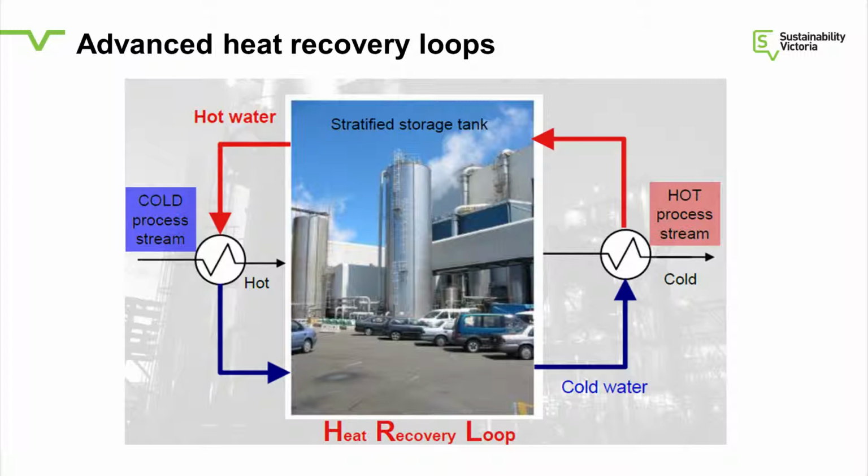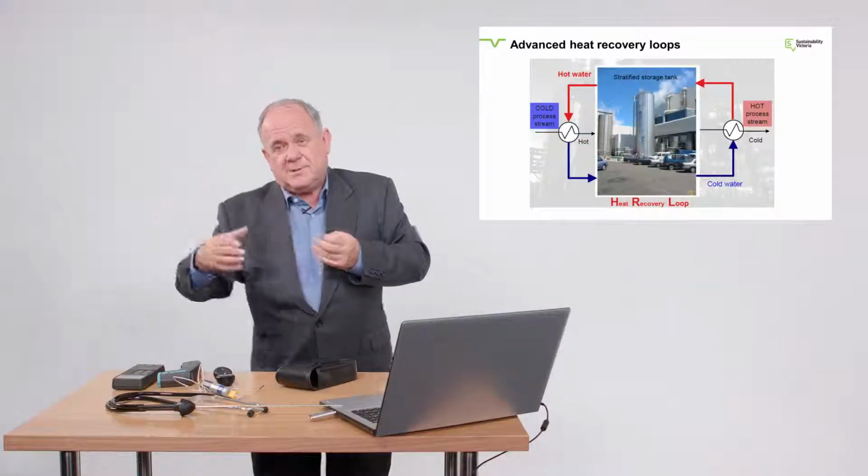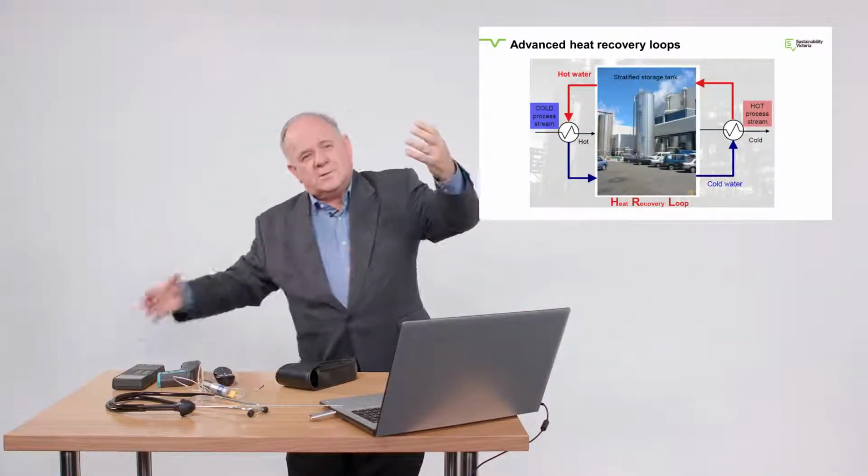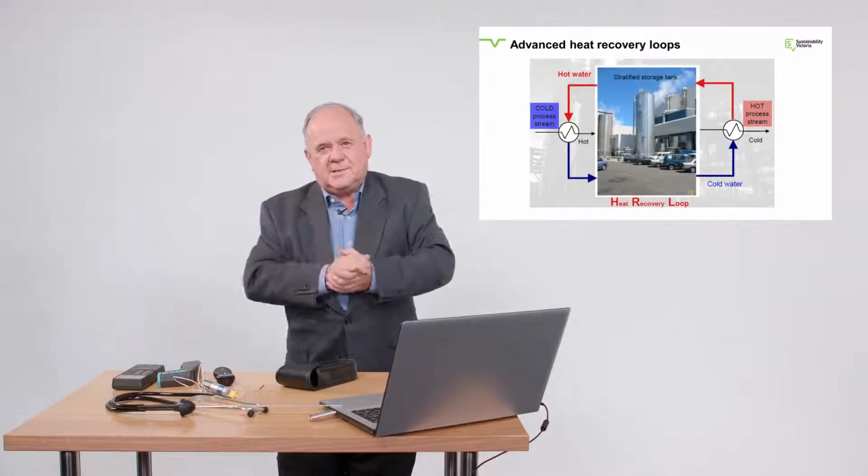It's very clever stuff, because otherwise you'd be spending energy to remove the cooling and energy to remove the heating. So what you're doing is using this big tank as a heat transfer to basically move waste cooling to a pre-cooling process, waste heat to a preheating process.